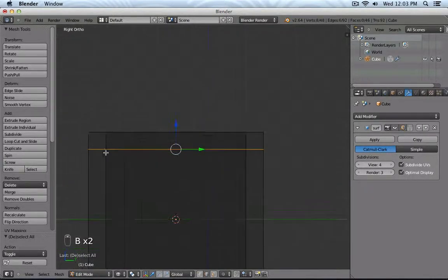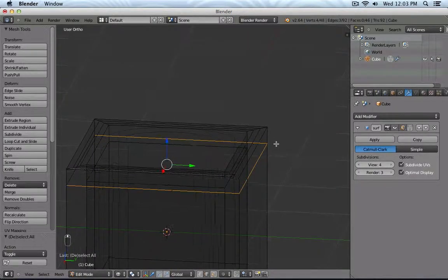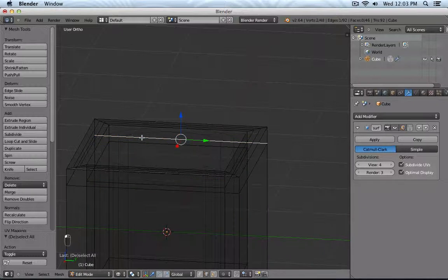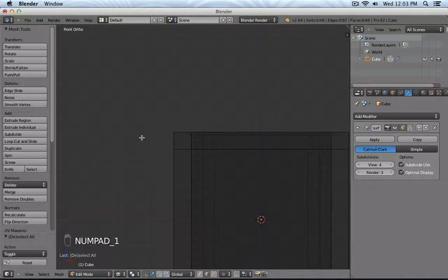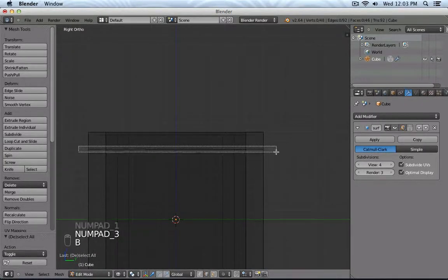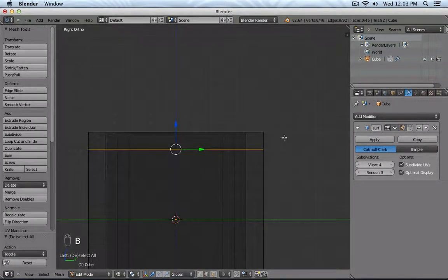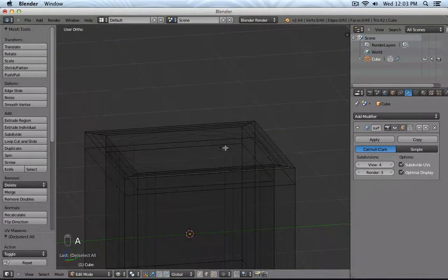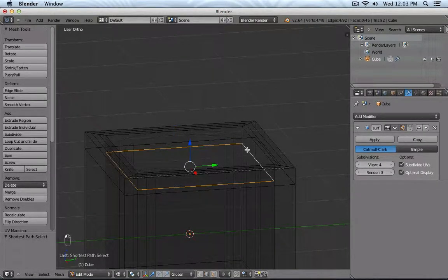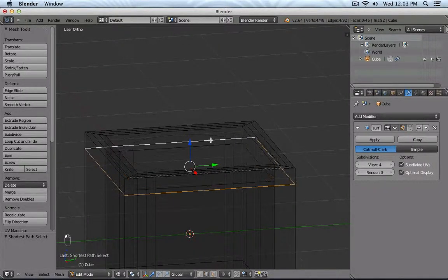So this is similar to the way left click and shift left click works to add and remove parts of my selection, and I can quickly simply drag over it with the middle mouse button and B. Or I could also, for example, press Alt or Option and then click on an edge, and then you see it selects the complete loop cut or the ring.